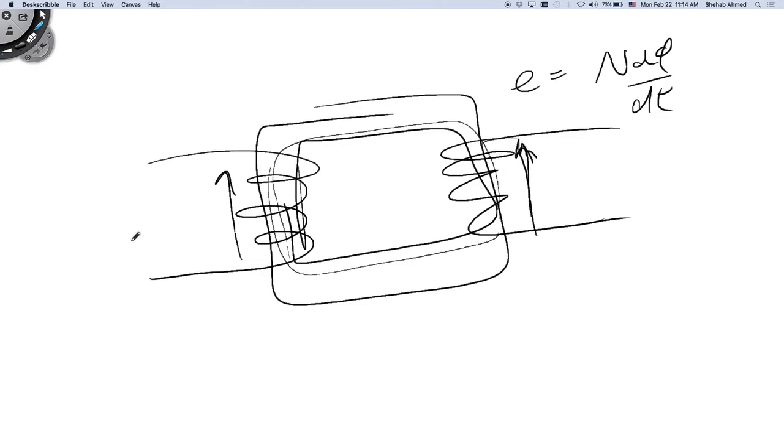So I put a voltage here, I supply the transformer with the input from the generator. This pushes current. This is sinusoidal, so the current flowing through is sinusoidal. It goes through this winding. Right hand rule generates a flux with a certain polarity that flows in the core. This is a time varying voltage, hence a time varying current, hence a time varying flux that's flowing in the core. Links both primary and secondary.